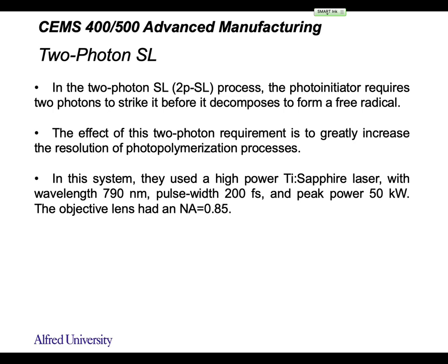For the 2 photon polymerization, you can control the process, right? So usually for 2 photon polymerization, you have to reach a really high light intensity to start this 2 photon polymerization. That means you have to focus your laser. You have to quench your laser into a pulse laser so that you can reach a really, really high intensity for that polymerization to happen. So that means you can focus your laser to a really small spot, and that polymerization process will only happen at this spot, right? Not here, not this area.